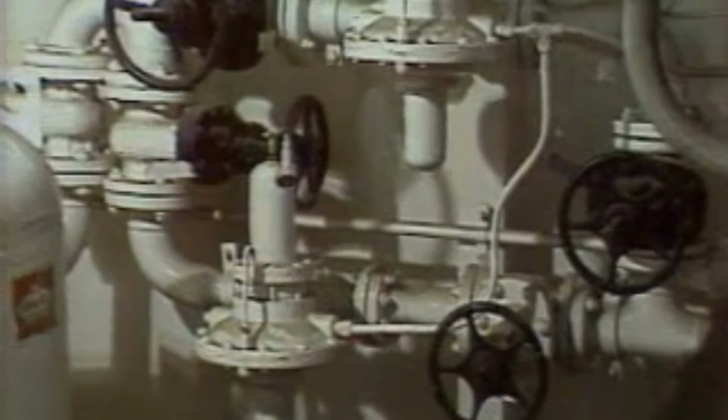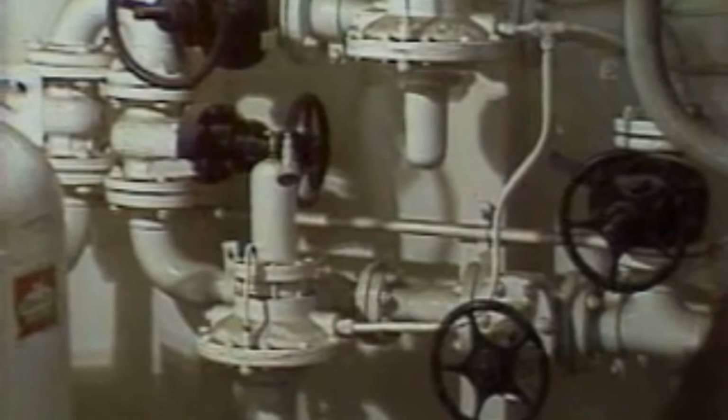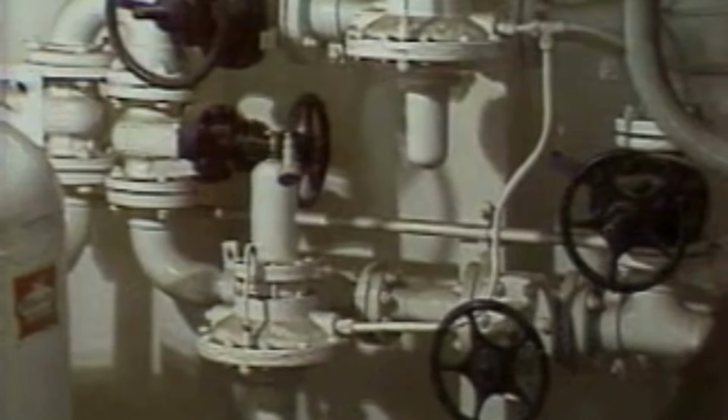Moving bulk is no more complicated than that, but there are some problems you can encounter. The most common one is a plugged line. Plugged lines occur usually because of moisture in the air system or condensation in the lines. The transfer air usually comes from the rig's air supply system. Water condenses in these lines pretty easily. There's supposed to be a drying system to dry the air out before it enters the system, but sometimes when the dryer isn't operating right, moisture can pass through with the supply air.